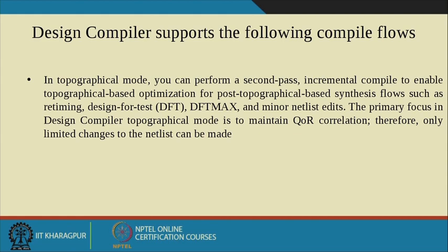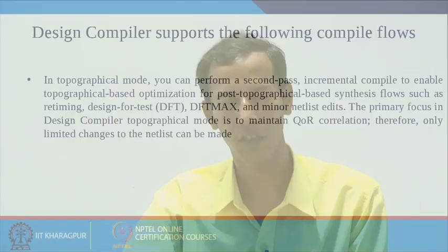This design compiler supports the following compiler flows. In topographical mode you can perform a second pass incremental compile, and also for DFT or DFT Max you can do this. In each of these we basically use incremental compilation mode to improve the quality of results.